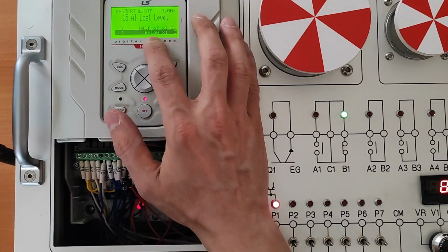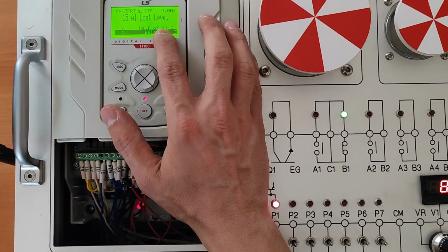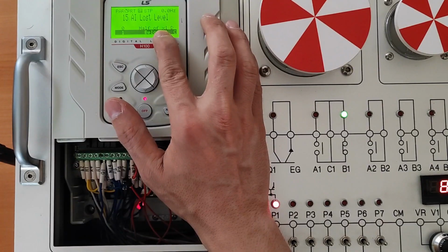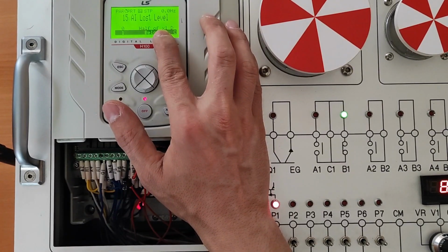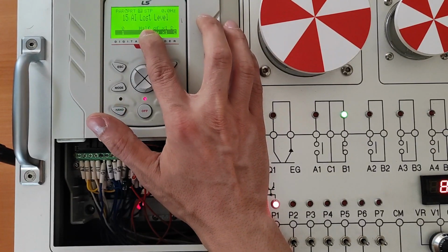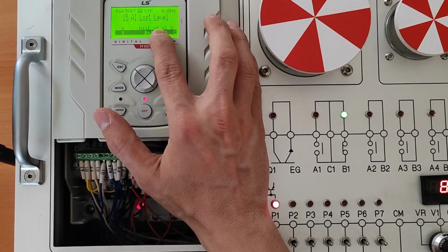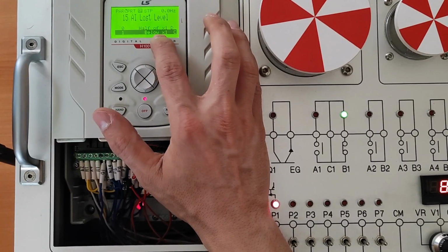Okay, moving on to PRT 15, we said that we can consider two different operational modes. The first operational mode specifies that if the original reference point you set for the analog input decreases to less than 50% of that value, the system will trigger a loss of command signal error. For example, half of 4 milliamps is 2, so if it goes below 2 milliamps, I detect the loss command error. The second option indicates a negative response.